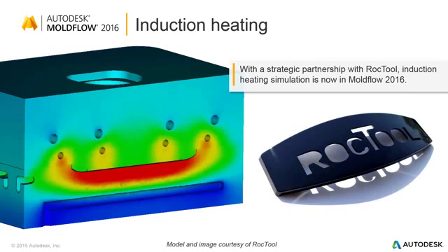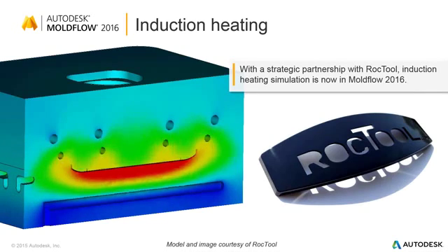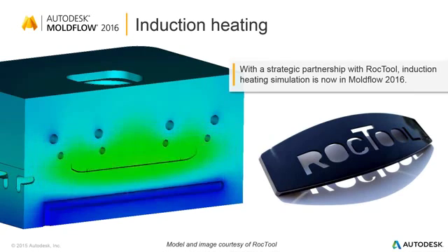So when you heat up the mold above the transition temperature and then inject the plastic into it, you get a really good surface quality finish on the side where the mold is above transition temperature. Now, the heating actually happens very quickly.